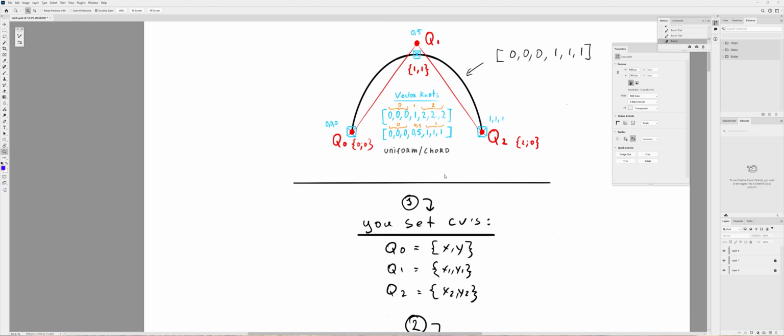If we don't have the spans at the beginning, we have the curves, it approximates using, as I said, the control vertices, or vice versa. Once again, there are a lot of ifs. But the overall result is that the intervals of the spans will be defined by the actual distances, or the chordal lengths, of the edit points.